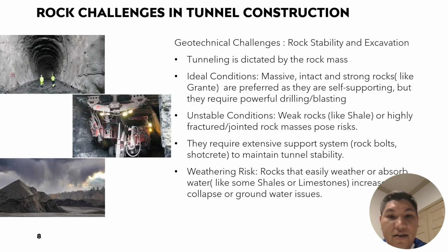The rock challenges in tunnel construction. The general challenge is the rock stability and excavation. The tunnel is dictated by the rock mass. In ideal conditions, massive, intact, and strong rocks like granite are preferred. They are self-supporting, but they require powerful drilling and blasting.